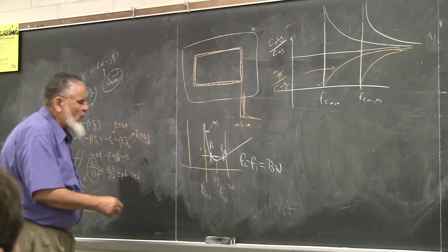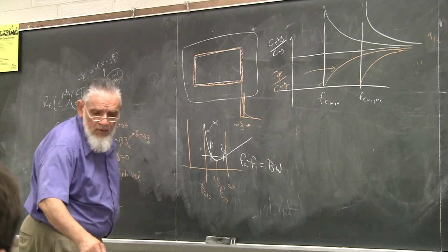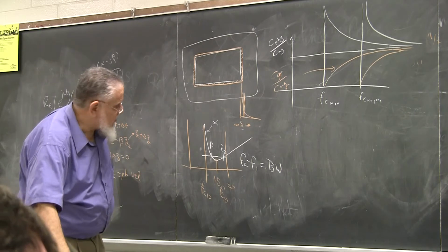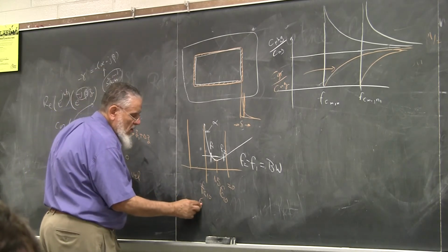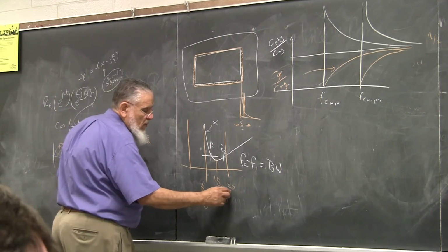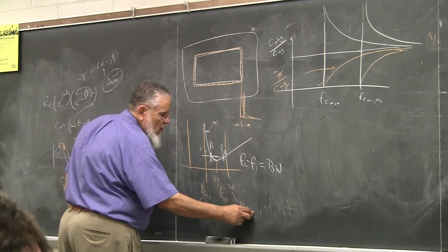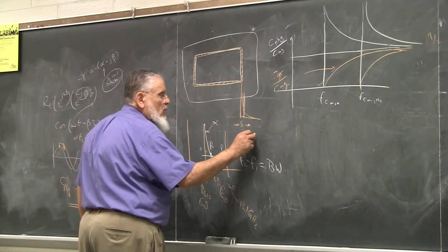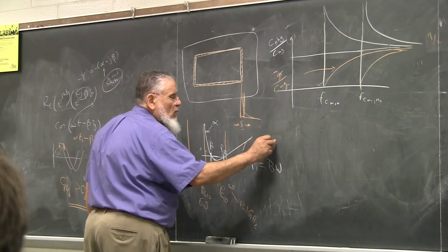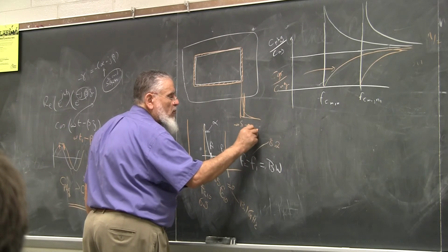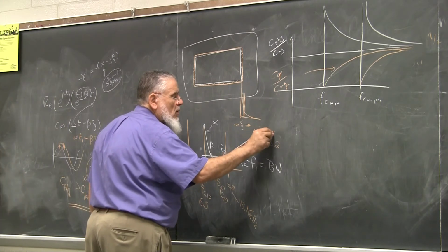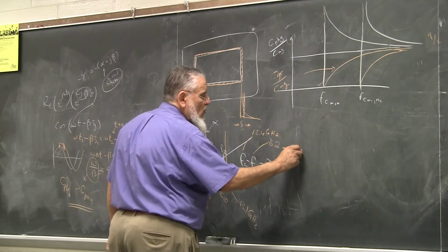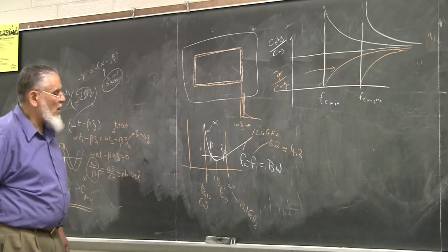The example I gave you before was the X-band waveguide, which is this one here. This is X-band, the 0.9 inch and the 0.4 inch. This is the one that you saw there. This one here is 6.5, and this about 13.1 gigahertz. And typically we do 8.2 to 12.4 gigahertz. If you take the difference between those, that's about 4.2 gigahertz.